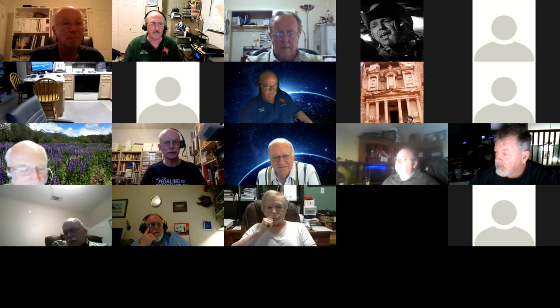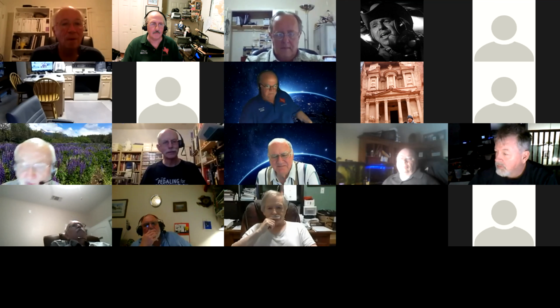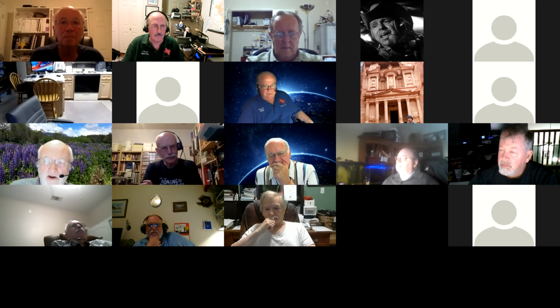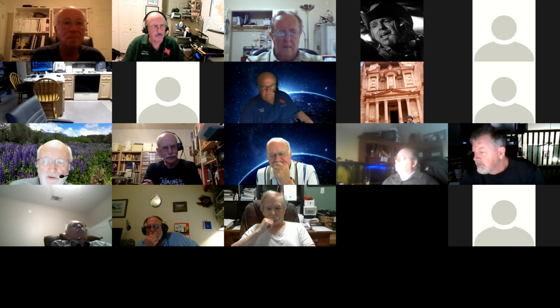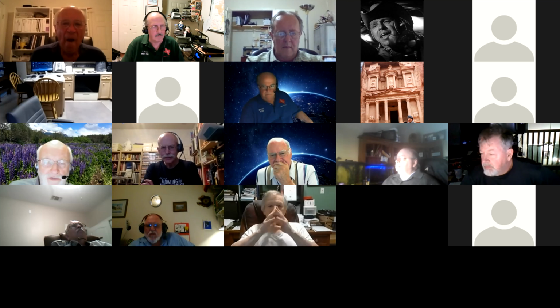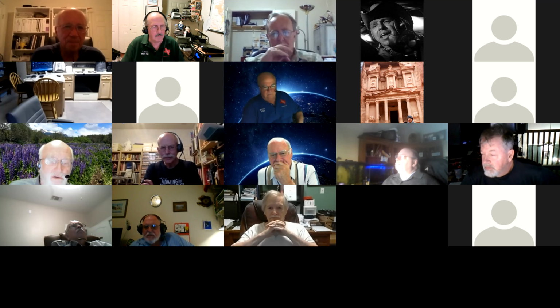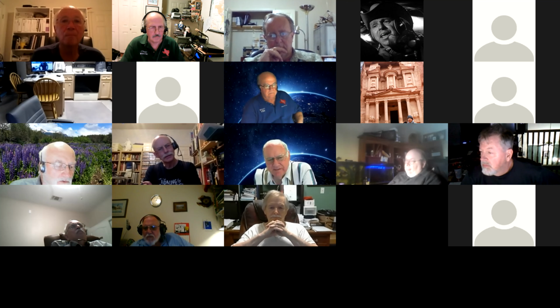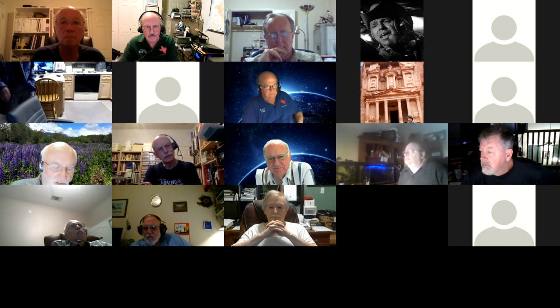Go ahead. Okay, so you understand what the Smith chart display is: it's reactances and resistances on a complex graph. Sometimes when you look at a transistor or some other component that has characteristics that depend on frequency, they will plot those over a frequency range and put them on a Smith chart, just because it's such a good way to show that. So a lot of times you will see a Smith chart plot showing impedance values over a frequency range, just because it's a good display tool.